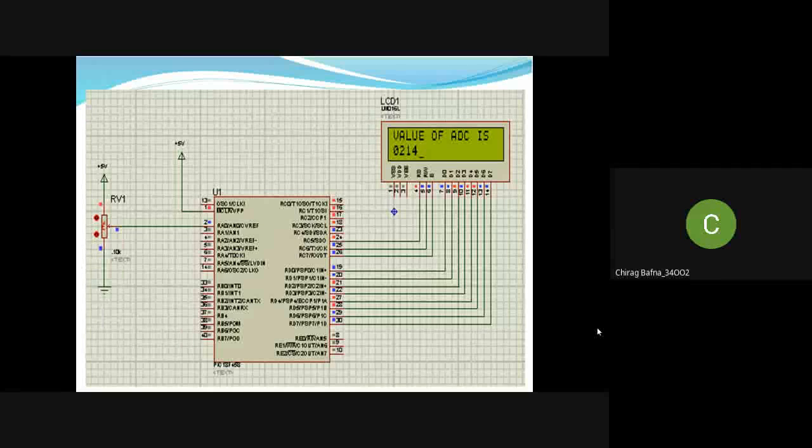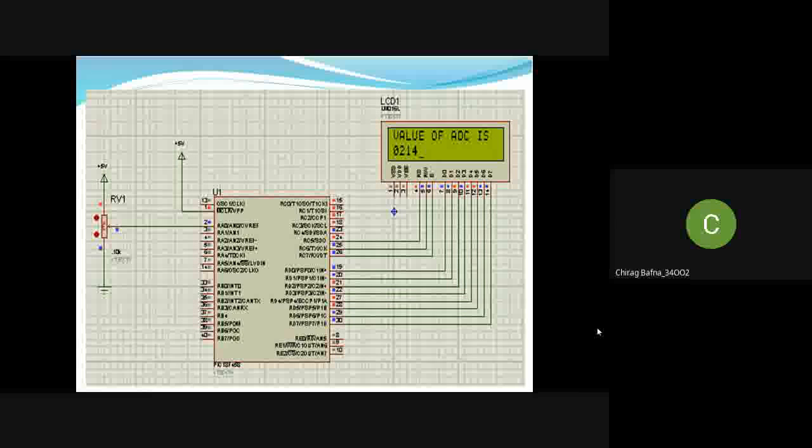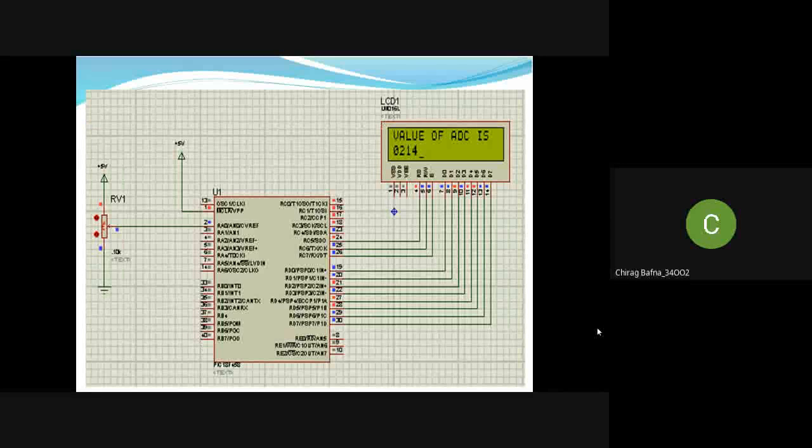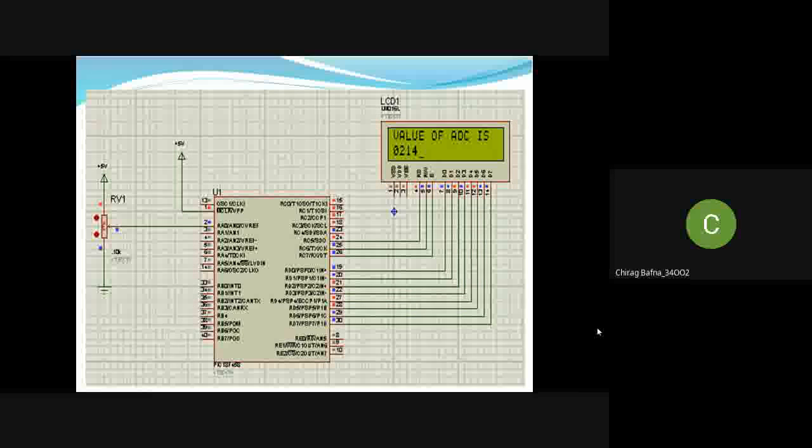Here is the interfacing diagram of the analog to digital converter. The D0 to D7 data pins of the 8-bit ADC provide an 8-bit parallel data path between the ADC chip and the CPU. In the case of a 16-bit parallel ADC chip, we need 16 pins for the data path. In order to save pins, many 12 and 16-bit ADCs use pins D0 to D7 to send out the upper and lower bytes of the binary data.